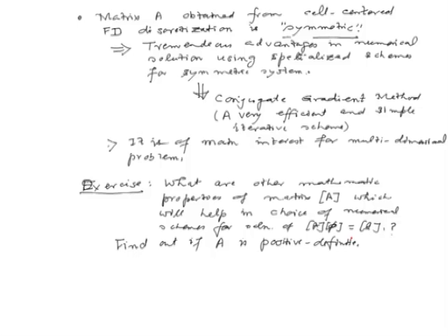I will close this cell centered approximation with a remark that this scheme we use exclusively in the solution of Navier-Stokes equations. We will have what we call a pressure Poisson equation, an elliptic equation, and for its solution we will choose pressure nodes to be at the centers of our cells, and the resulting system matrix would be definitely symmetric, and that will help us in the solution.